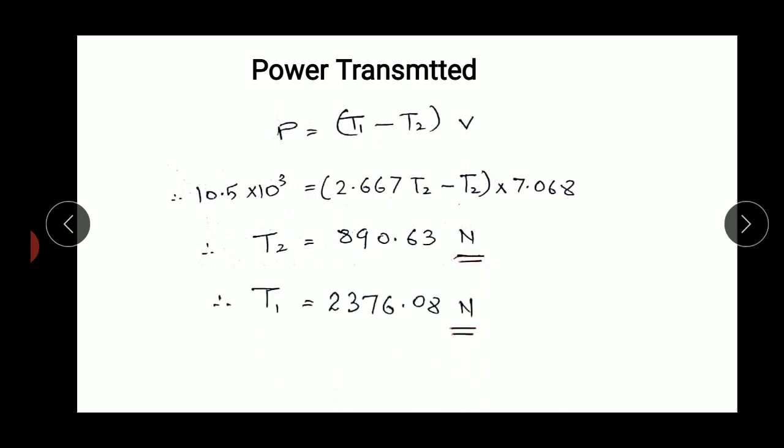Then put it in equation number 1. You will get T1 as 2376.08 newtons or 2.376 kilonewtons. So T1 we have finally found, but still our question is incomplete because we have to find stress, not tensions.